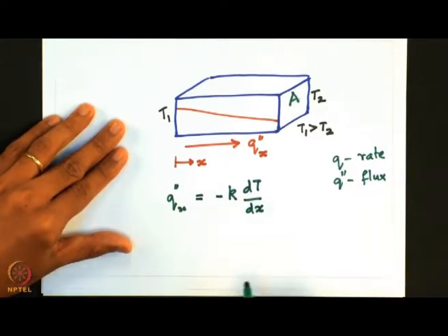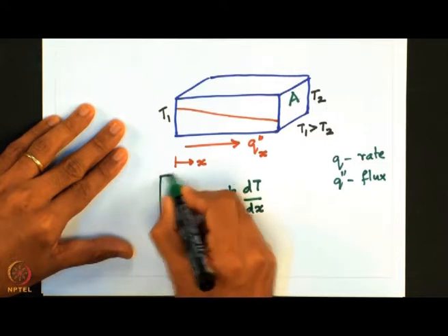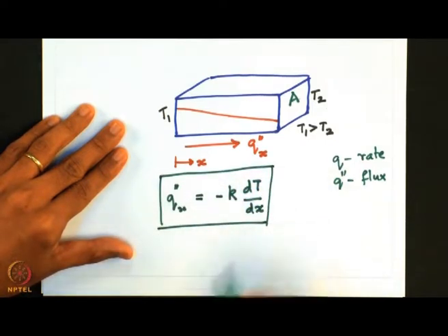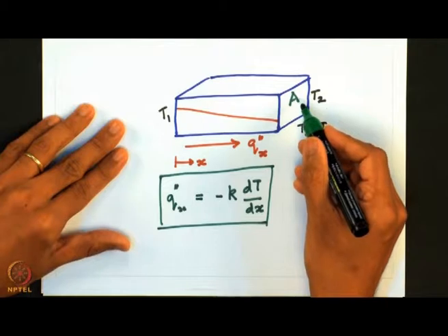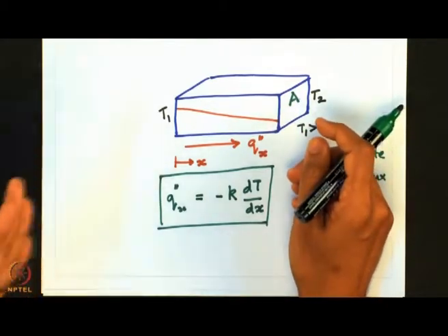So, that is the relation between the flux of heat transport and the corresponding temperature gradient, which is the driving force. Suppose A is the area of heat transport. Remember that the heat transport is from one end to the other end, across the cross section of the slab. And so, the rate of heat transported from one end to the other via the cross section of the slab is given by the flux multiplied by the cross sectional area.